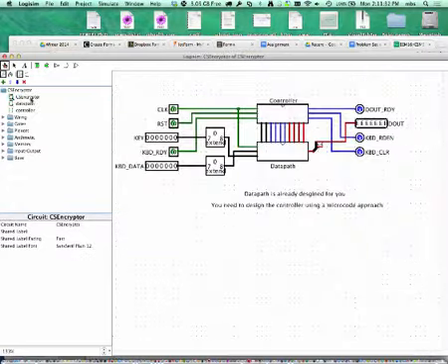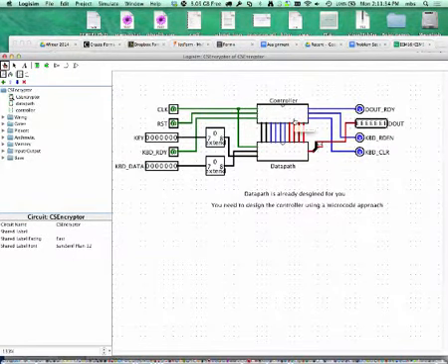And again, if you go back to the top level design, you see they are wired up to the controller. In the controller, in the baseline design, you are only allowed to use a ROM and a register. You can pick the ROM to have any number of data bits, any number of address bits, and your register can have any number of bits, but you cannot use any other logic. So it's a pure microcode design. And you'll be graded by how big the ROM is and how many bits you use in the state register.